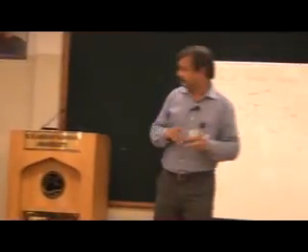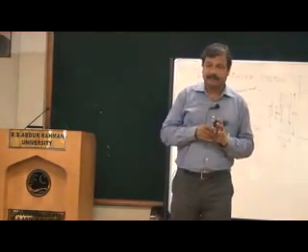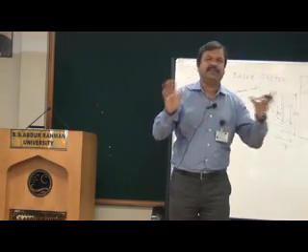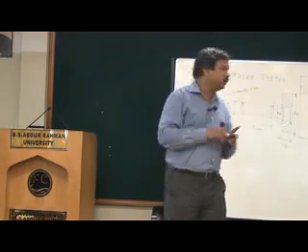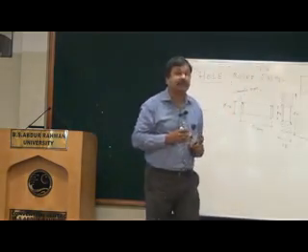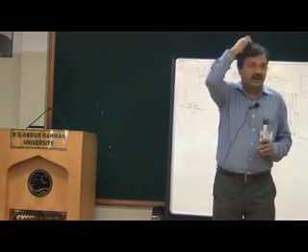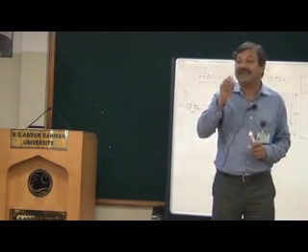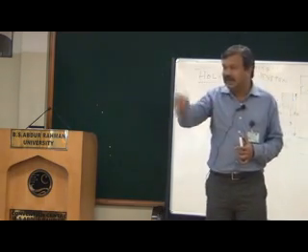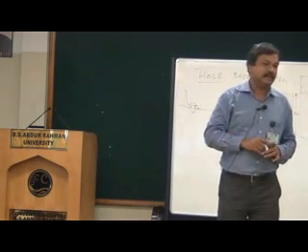Typically H7. 99% of the holes will have the tolerance H7. Why H7? Because if you just drill a hole and perform a manufacturing process called reaming, which can be done in the drilling machine itself, I will be able to realize an H7 tolerance.